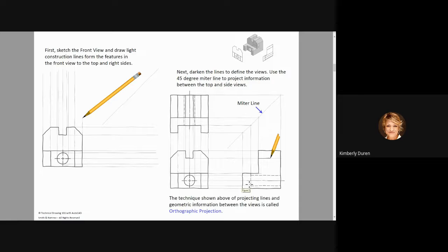And then from this center mark, if you have a bullseye, you've got to have an axial center line. Now, why doesn't that come all the way out beyond the material here? Because the hole starts back here at the back of this notch. So you just come beyond the circular object, not beyond the square object, but the hole starts right here. And so you just go outside a little bit. We've got a line, one dash, and then another line. You don't have to have multiple dashes, you guys. It's going to start looking like a hidden line, which is uniform dashes like this.